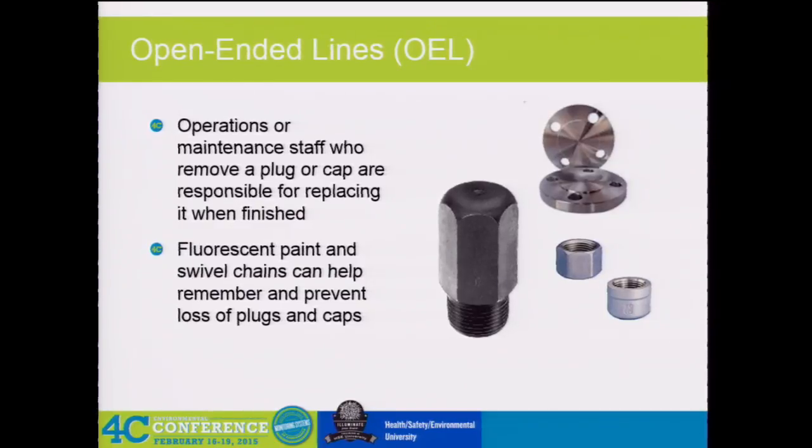But so this is what we're talking about. So you have, this meets the definition, correct? Has 2 valves. But how do I truly get all of this cleared? You're gonna still have process. By the time I close this one, because I'm closing my upstream valve first, I still now have all of this filled because I can never truly purge it.